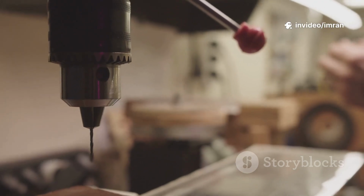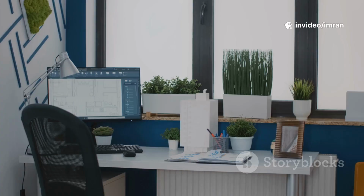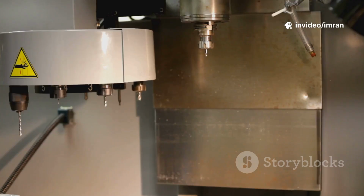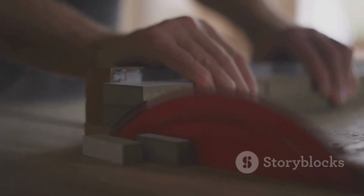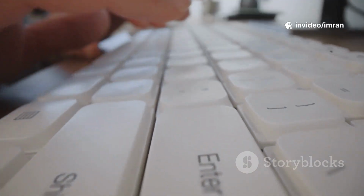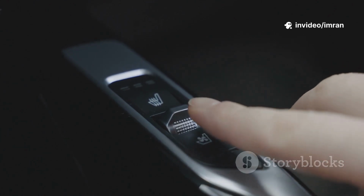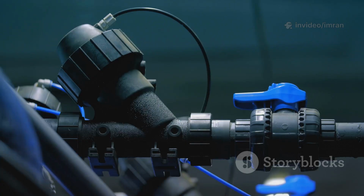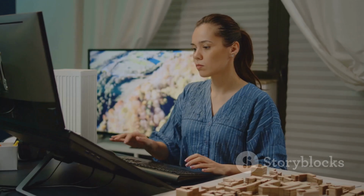A fantastic feature is the seamless integration between the Trim and Extend commands. When either command is active, you can switch to the other just by holding down the Shift key. For example, if you're trimming several objects and you notice a line that needs to be extended, you don't need to end the command. You can just hold down the Shift key, and the Trim command will behave like the Extend command. This allows you to fluidly switch between cutting and lengthening within a single continuous operation.